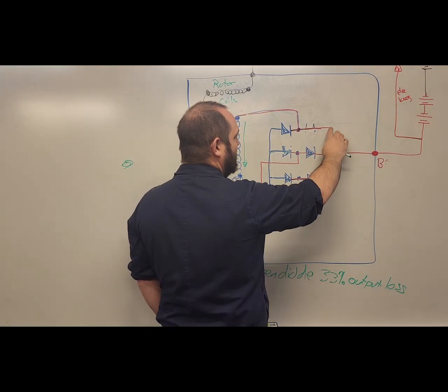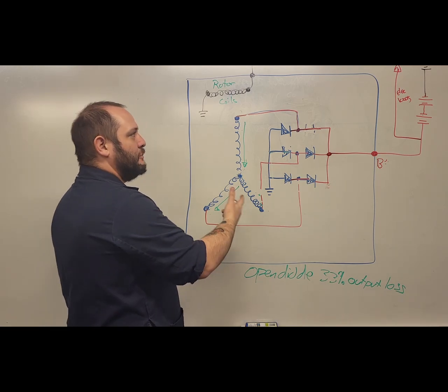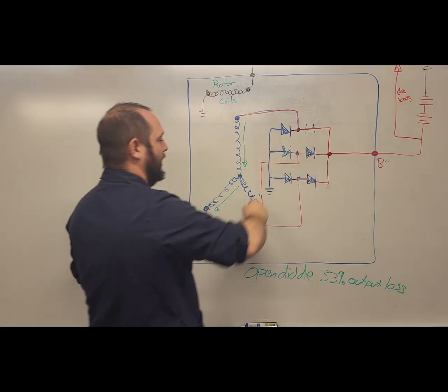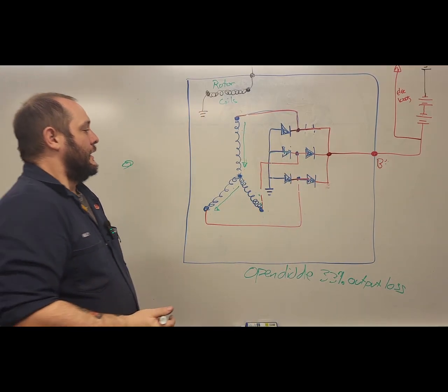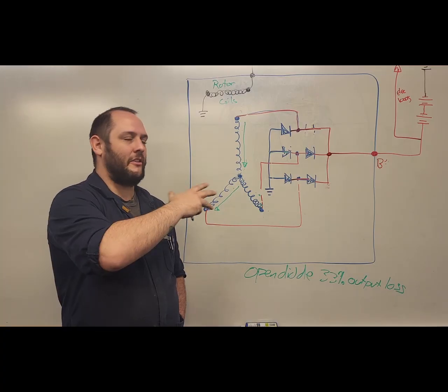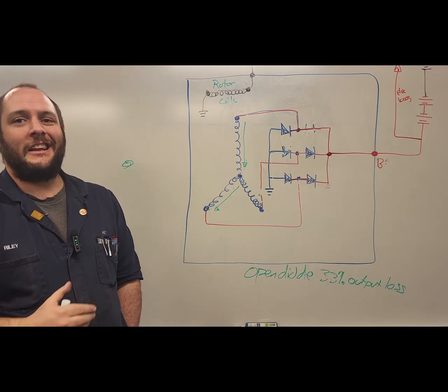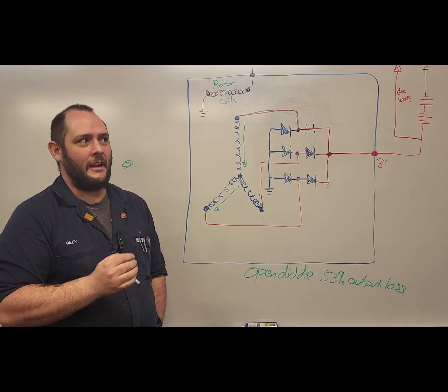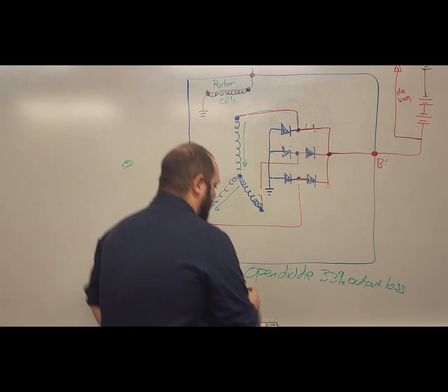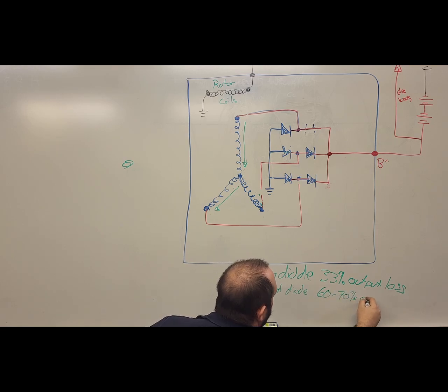Alternatively, it has a nice, easy, short-circuited path back on that ground circuit. Now I'm supposed to be returning on that ground circuit, but I also have a nice, easy path on the positive side to just flow right through those coils. So on any of our three pairs of legs on this stator coil, I'm going to have output current bleeding back through the stator because of that shorted diode on any two of the given pairs. So that's going to yield me on a shorted diode my 60 to 70% output loss.